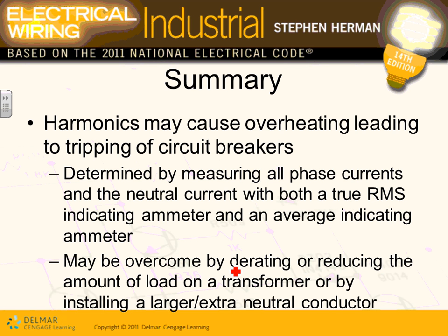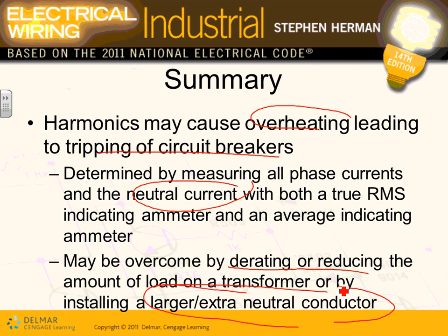So the harmonic will overheat your circuit breakers, and your neutral current will also be affected. You can overcome that problem by derating, or reducing the amount of loads on the transformers, or extra neutral connectors. Or if worse comes to worse, you have a filter for your system.